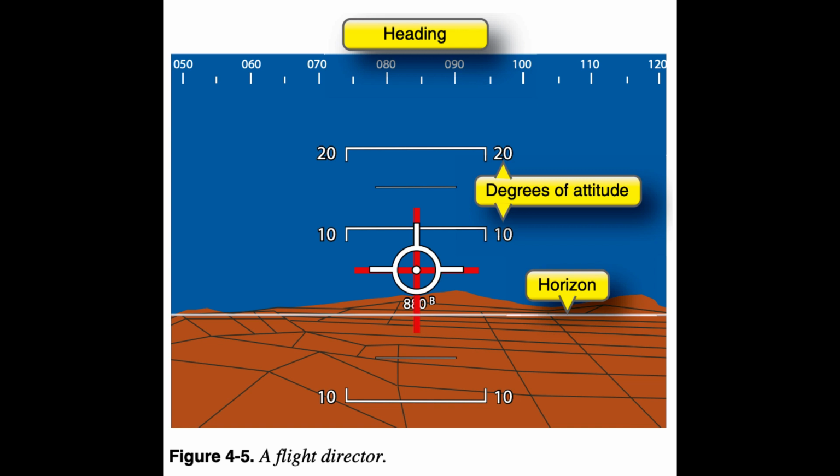Without autopilot engagement, the FD presents all processed information to the pilot in the form of command bar cues, but you must manually fly the airplane to follow these cues to fly the selected flight path. In effect, you tell the FD what needs to happen and the FD command bars tell you what to do. This adds to your workload, since you must program the FD for each procedure or maneuver to be accomplished, while actually flying the aircraft. In many cases, you will have a decreased workload if you simply disable the FD and fly using only the flight instruments.